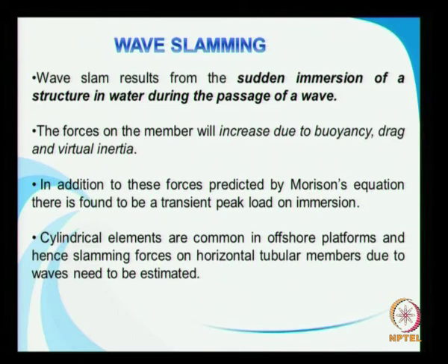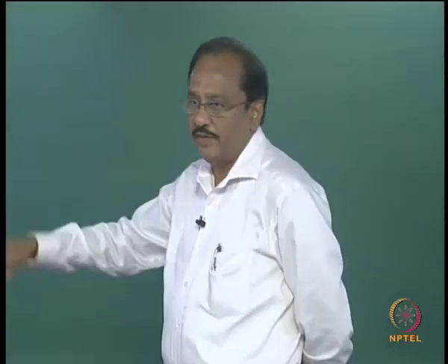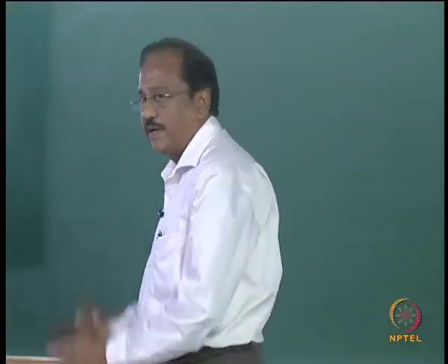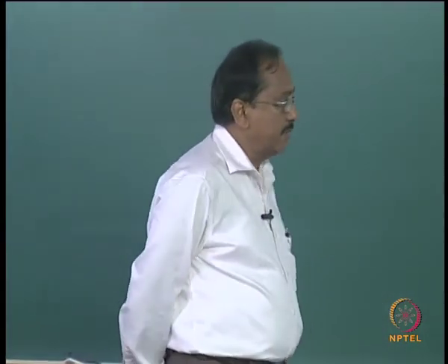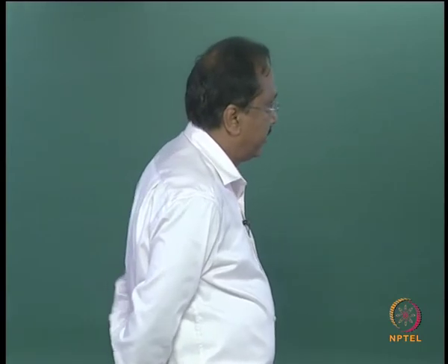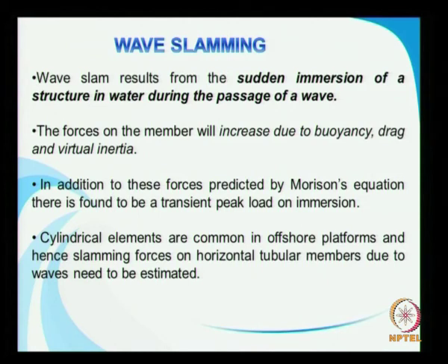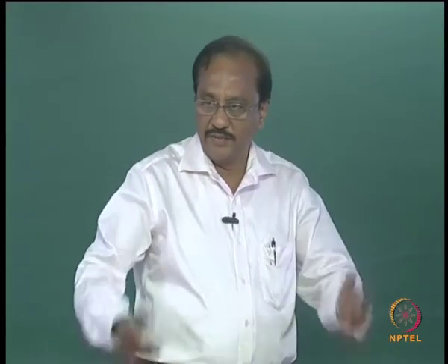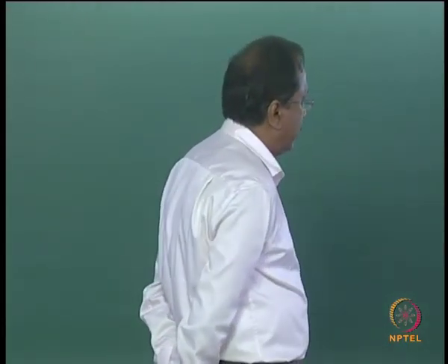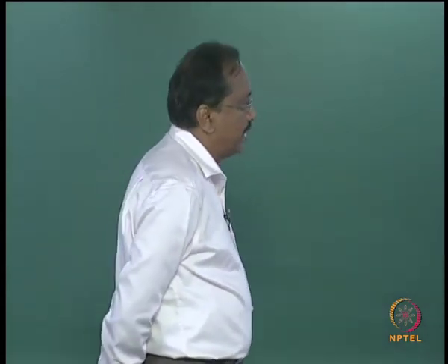In addition to these forces predicted by the Morison equation, there is a transient peak load on the immersed body. Unlike a sinusoidal variation, it is a sudden transient phenomenon, which needs to be taken into account while designing these members. Cylindrical elements are common in offshore platforms, and hence slamming forces on horizontal tubular members need to be estimated. Only these horizontal tubular members will have the slam force due to waves.